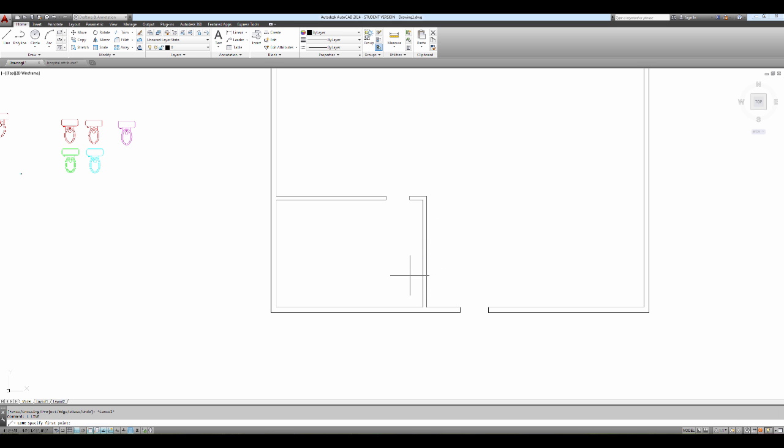It's going to be for like a broom closet or something. So it's going to have a little tiny space in here. So I'm going to just go and put in a small little wall. We'll come back maybe 2 feet and come down like that and offset that 4.5 inches.